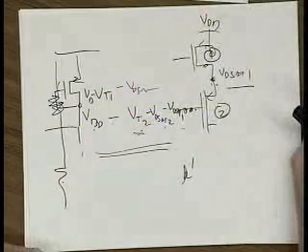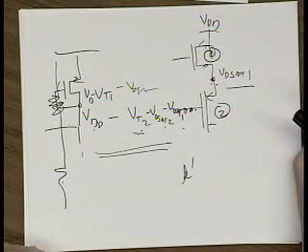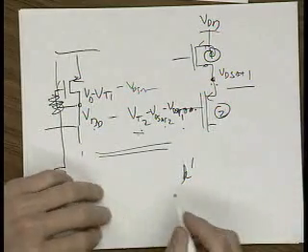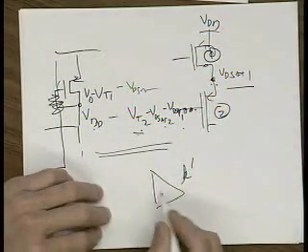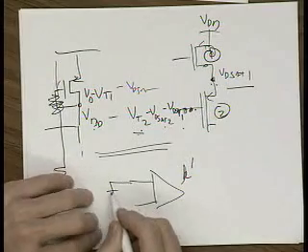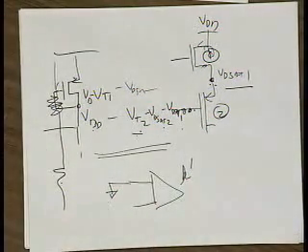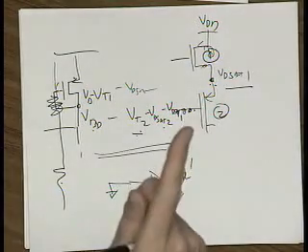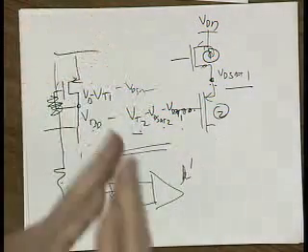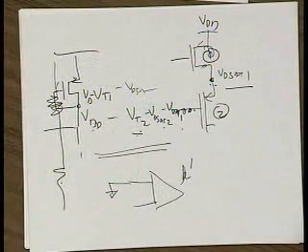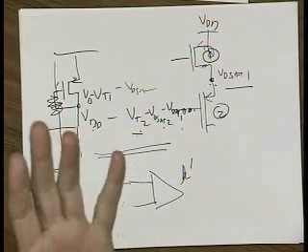How would you generate the bias voltages for the replica bias then? Well, what I do is just ground the inputs. The idea is to take the inputs, you don't have an input into the replica circuit, and set those to 0. Then that circuit sets up a bunch of DC voltages that you can use over in your circuit. They're not a function of the input values.